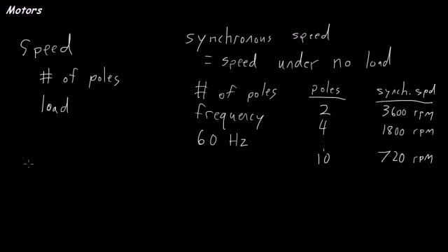Another concept that is related to speed is called slip. Slip is basically the difference between the RPMs at synchronous speed minus the RPM that the motor is operating.